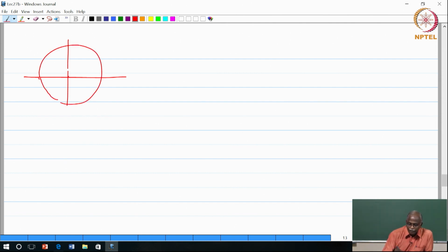I would have zeros which occur as quads. So, that means there is a zero here at the conjugate location, and at the reciprocal locations also. So, if this is z0, this is z0 conjugate, this is 1 over z0, this is 1 over z0 conjugate. So, you will get quads of this type. This is because of the symmetry.